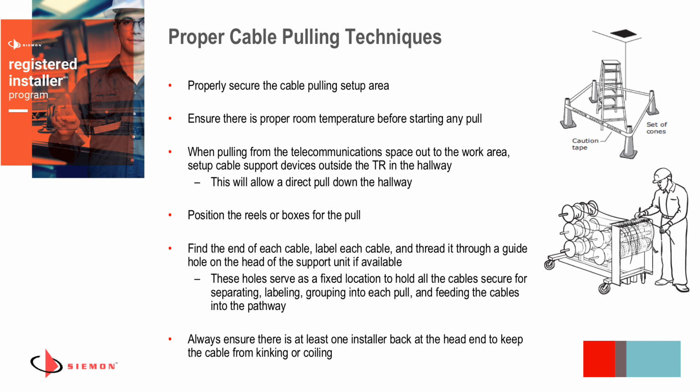But you always have to make sure that someone is monitoring those cables during the pull. You can't have one technician just grabbing the cables and pulling them, because you don't know what's happening at the head end. You don't know if one of those reels is close to empty. You don't know if one of them has got stuck or is getting tangled along the way. So it's important to have somebody at that end at all times watching those cables to ensure proper dispensal.